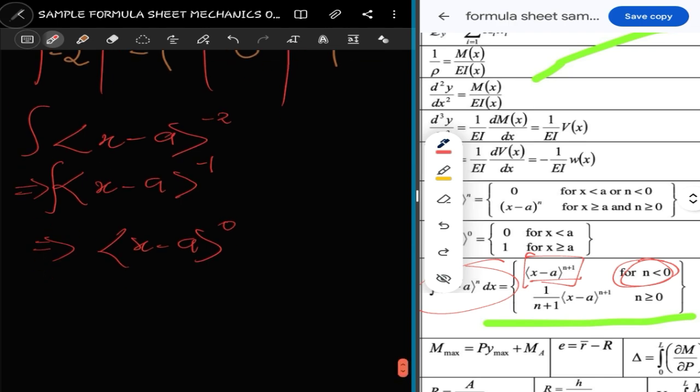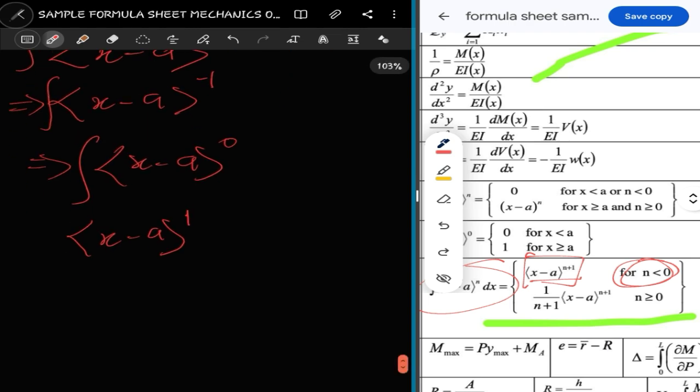But before I do the integration, I check, right? So before you do the integration, it's just 1. When I integrate, I get 0. I don't do anything to it. But if I integrate this particular one, what I get is Macaulay bracket x minus a to the 1. When I get this one like this, the natural sense is to just bring the 1 I have here, right? Basically, there's one attached here, so it's still the same thing, right? So just 1, and I bring that number that I had down. This is what we get.